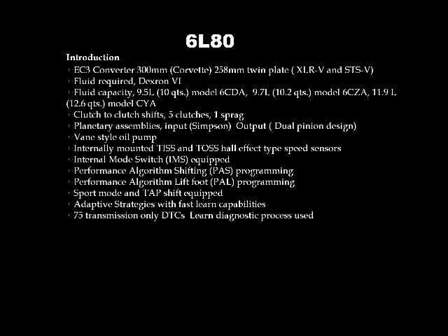Is going to be Dexron 6. Now, most of you are aware that Dexron 6 came out about this time frame. The reason for it being developed was the introduction of these 6-speed transmissions. These 6 speeds do not turn the fluid over quite obviously like the 4 speeds did as far as flow through the coolers and so forth. And there's also quite a bit more clutch loading in these transmissions, so they felt they had to have a different transmission fluid, and that, of course, was Dexron 6. You see on your screen the capacities depending on which transmission you actually have. So bottom line is you're going to have different fluid capacities depending on what you actually have for a transmission.